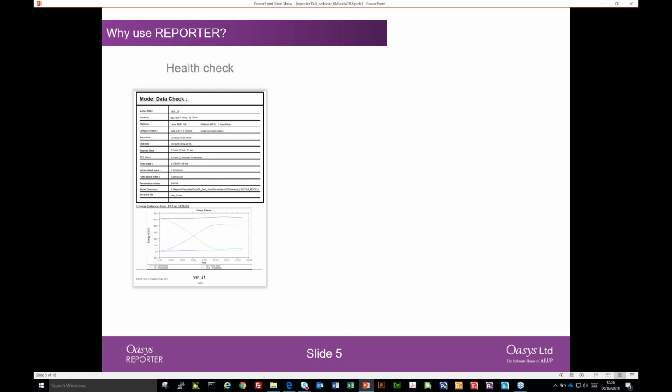You might also want to create a health check for your LS-DYNA simulation. You could look at the OTF or message files and determine the termination status and report on things like any added mass or energy balance. And this could be a report that you ran automatically on your server after every LS-DYNA analysis to give you a dashboard of health checks for your LS-DYNA analysis.